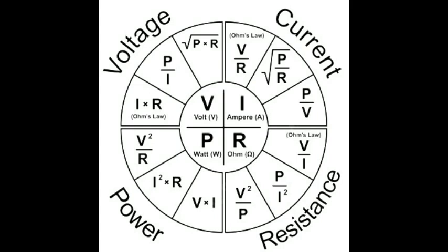For formula number 4, it's Rx, meaning that we're missing a value. We're missing one of the resistor values, but we have our total. So it would be 1 divided by 1 over our total. Now, our total always has to be in this position. If you put it in another place, you're going to have a wrong answer.